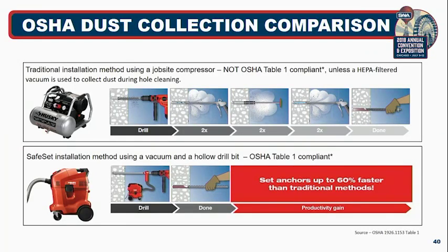Then the hole cleaning that I was talking about for adhesive anchors, once again, there's no industry standard that manufacturers have to follow as far as hole cleaning is concerned. Some manufacturers might say, okay, our hole cleaning process is drill out the hole, blow it out twice with compressed air, brush it out twice with a wire brush, blow it out again twice with compressed air before you inject adhesive to establish a clean hole, right?